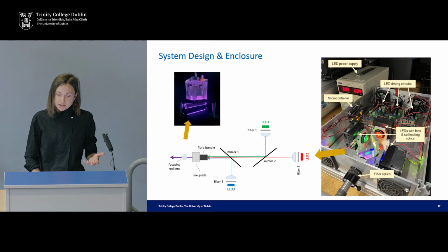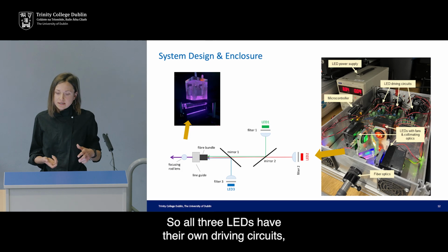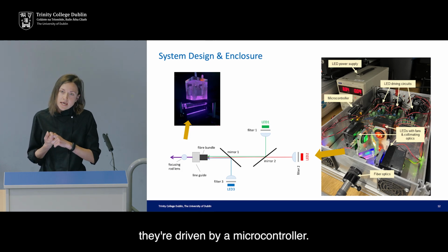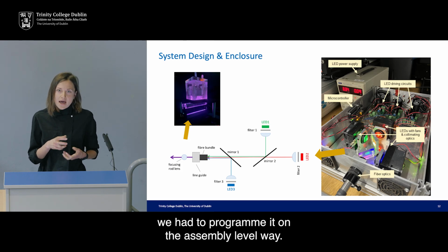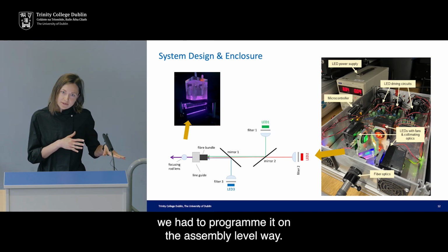That's how we built it. All 3 LEDs have their own driving circuits. They're driven by a microcontroller. And to achieve the desired microsecond accuracy, we had to program it at the assembler level.